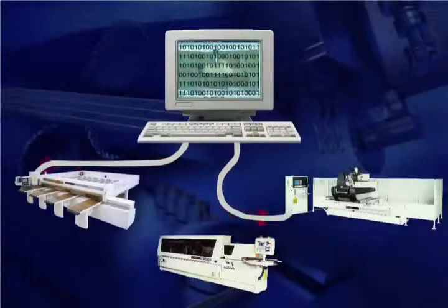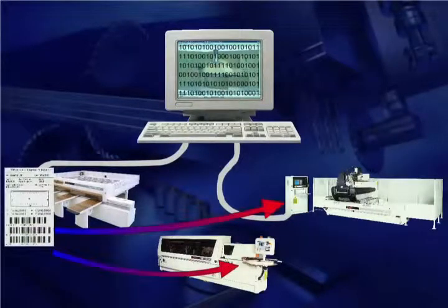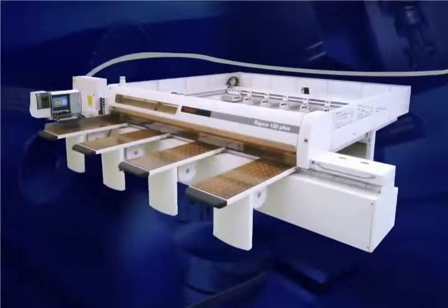Machine programs for the panel saw and CNC boring routing center are directly transferred from the server to the machines, while the bar-coded label printed by the panel saw links it to the programs existing in the edge bender and those previously transferred to the CNC boring routing center.